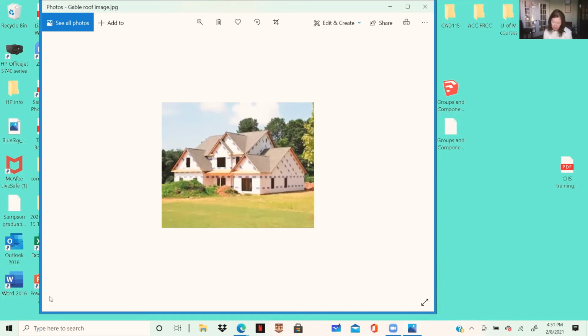You can use trusses, which increase the live load and help with labor costs, since the trusses are usually prefabbed. The cons are that the framing is more complicated than most flat roofs and more costly. If used over a living space, the headroom is limited on the edges of the room. Needs to be better insulated because of the amount of space, so that's more costly, and there can be sagging if they're not properly supported with a good subroof.